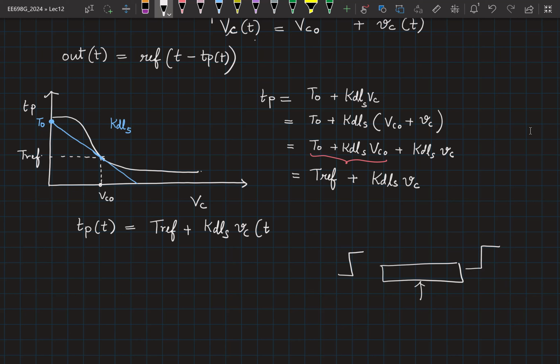So let's say the VC changed at the same instant as the signal is entering, right? Only after this edge has appeared at the output, I'll be able to measure the delay, right? So you see the effect of change in VC after the edge has appeared at the output. So in that duration, the VC can change a lot of times. It could potentially change a lot of times, right?